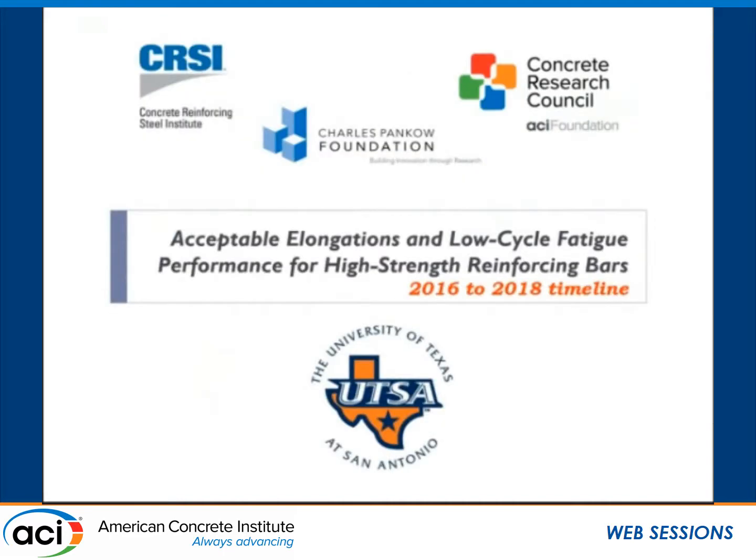Now, the current project we just started is, well, what do we do with all this? Where do we go with all this? Here we are trying to define what is acceptable elongation. So what do we put in the ASTM spec for those bars as acceptable elongation? What is acceptable low cycle fatigue behavior of those bars? I mean, this high is low, but how low can you go, or how low can you accept to go, or how high does it need to be?